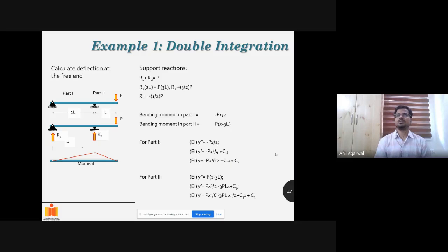See, both these methods that you mentioned, the conjugate beam method and the moment area method, by default have the words moment or beam, right? So they cannot be applied to trusses. If you have a moment, that is bending moment, then it cannot be applicable to trusses. That is obvious, right? For trusses, which method do you use typically for deflection calculation? Energy method, sir. Yes, one of the energy methods you have to use.